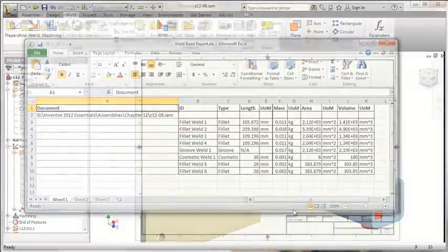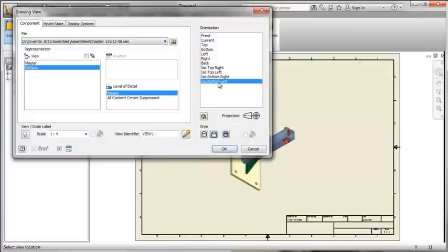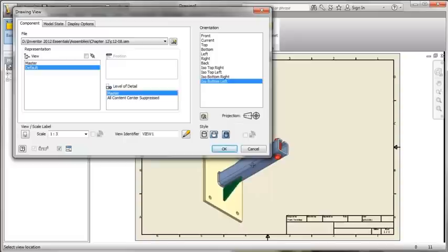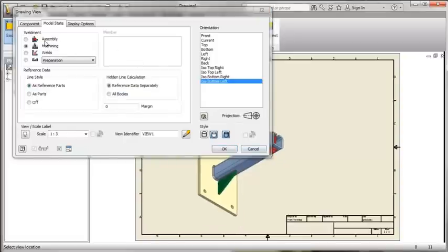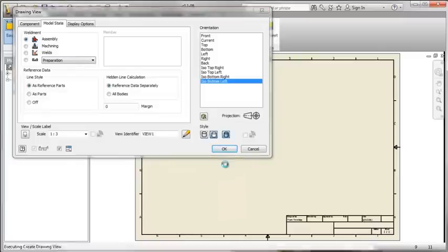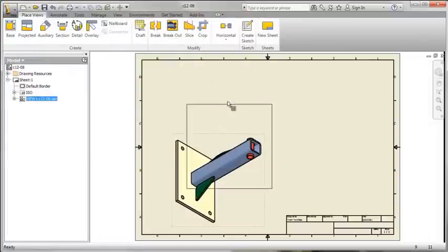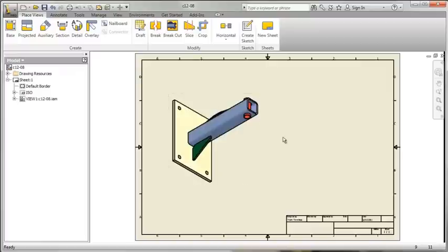One other thing we can do with the weldment environment is generate documentation for each phase of the weldment environment. So for example, here I'll tell it to go ahead and generate a drawing set to a scale. And in this case, I want to select the assembly state for my drawing. So this will be the raw components assembled together. I can tell it that I'd like to place another drawing view of the same assembly, or excuse me, in this case the same weldment, but in a different state.